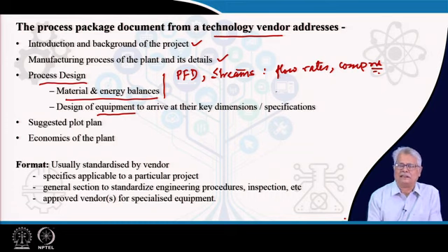Now, you have to provide safety against expansion of the piping and equipment. This is very important in process plants, because your installation temperature could be the ambient, but its operating temperature could be much higher, or much lower in cryogenic plants. This definitely requires provisions for either expansion or contraction of the equipment, which may require certain overpressure release, sometimes space, sometimes anchoring and things like that.